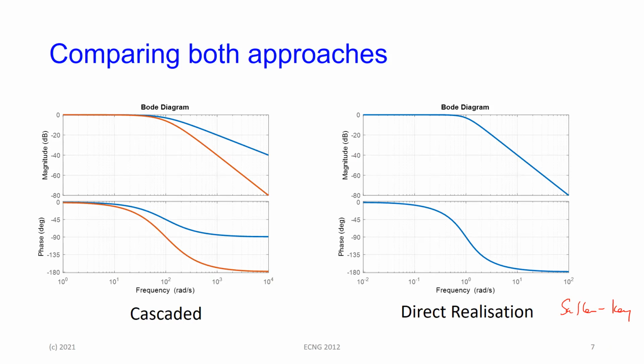They look identical. There is one little subtle difference. If you look at the performance here of the Sallen-Key, right around cutoff, you'll notice that the cascaded filter gives you a little bit more of a rounded transition. Remember, this is the passband, this is the cutoff here.